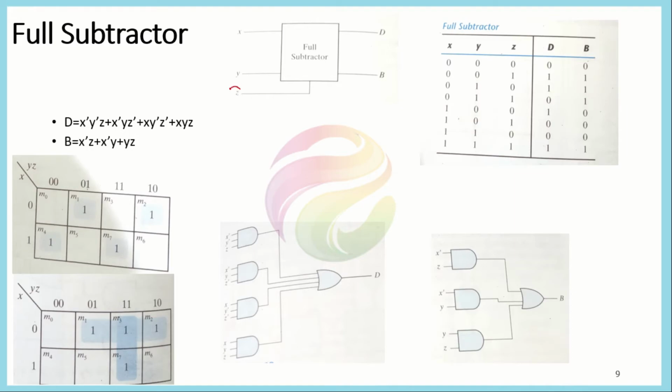Now if we move on to the full subtractor, we are assuming that we have an input from the previous column, or the borrow from the previous column too. So now we have to consider a 3-bit system, or 3-bit subtraction process. Again, we are representing the outputs in the form of the difference and the borrow for the next one. First, we represent all these terms as a combination in minterm form. We have a 3-bit system, so we are representing the 8 different combinations here. Depending upon the values of each of these bits, we write the truth table for the difference and the borrow.